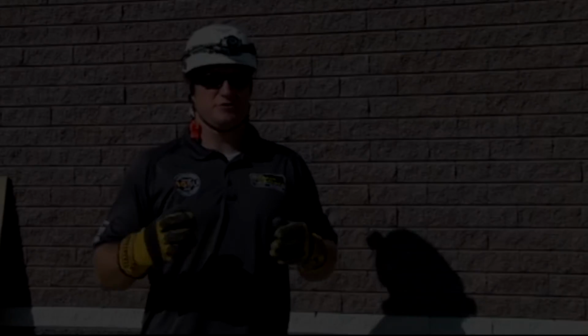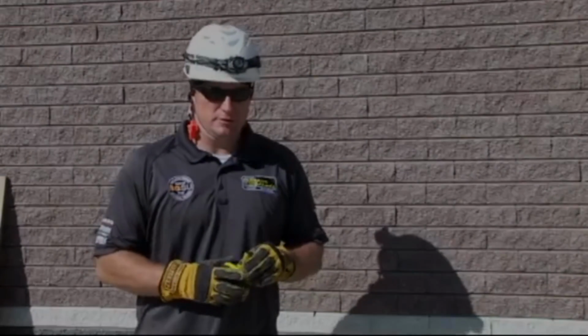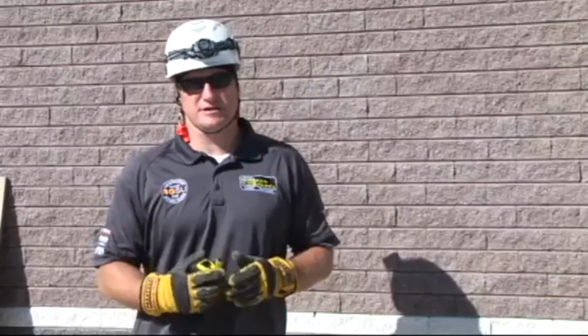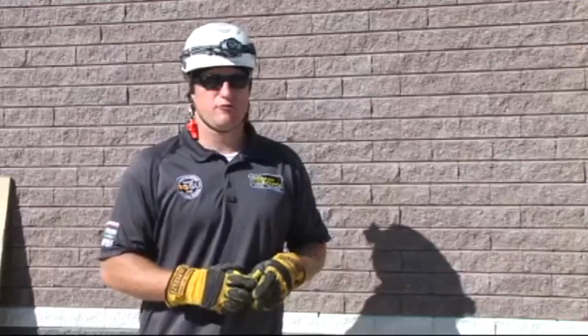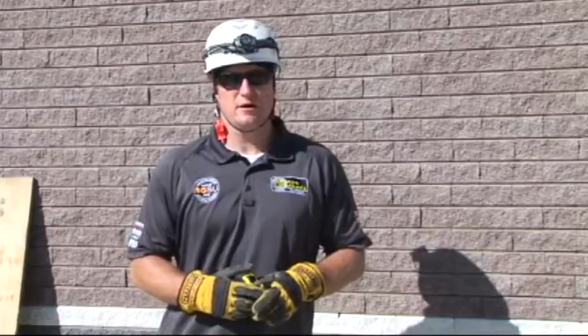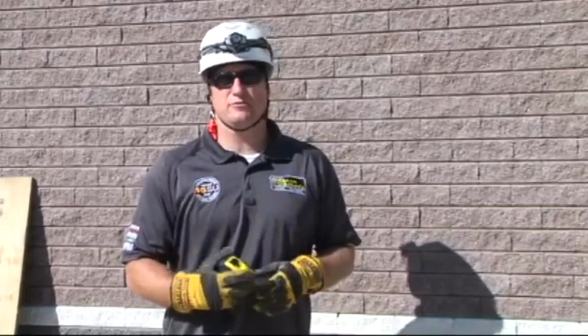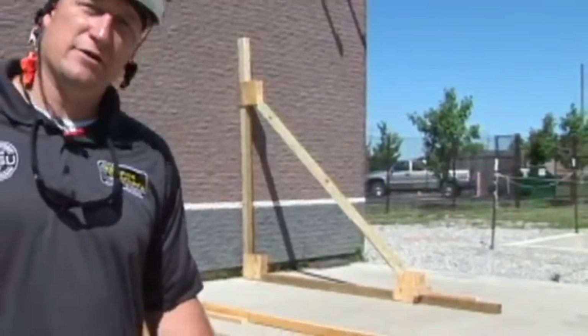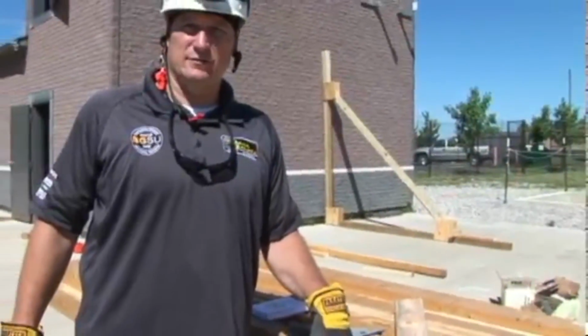This segment is about the construction of solid sole rakers. Typically we're going to build them as either 45-degree solid sole rakers or 60-degree solid sole rakers. If we're building on soil and not a surface like concrete or asphalt, typically we're going to choose the 60-degree rake because it has maximal height with minimal horizontal force application. For today's application, we're going to do a solid sole 45-degree raker and also discuss the variables for the 60-degree raker.